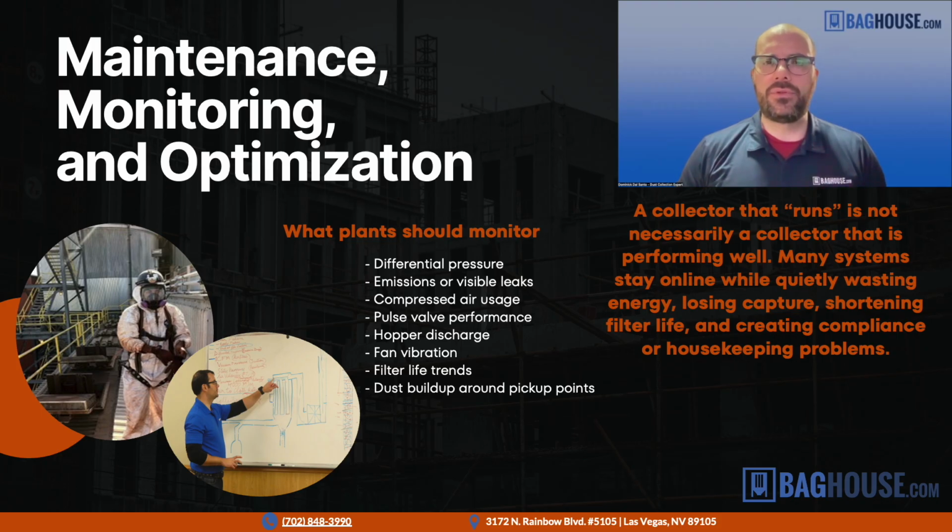Okay, lastly, just a few things we want to mention with maintenance, monitoring, and optimization. So every single dust collector in your plant should be equipped with a differential pressure gauge, and it has to be working. It's one of the most tedious and most routine things that we can do, but it's the first thing we mention whenever we do a visit: making sure the differential pressure readings are accurate and reliable. If we don't have that reading, and we can't rely on it and trust it, it affects everything we do with regards to maintenance, operation, planning. So we absolutely have to make sure that that system is functioning correctly.